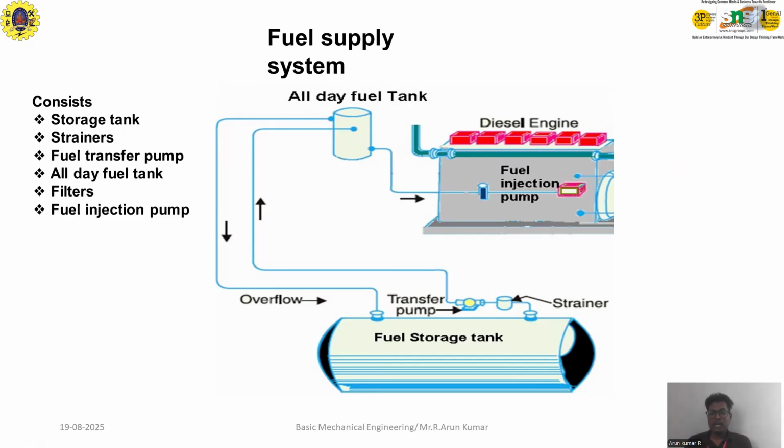Here the fuel is transferred by way of the strainer and a transfer pump. It passes to the all day fuel tank, and then from there it goes to the diesel engine. At the other end there is one valve, which is called the overflow.